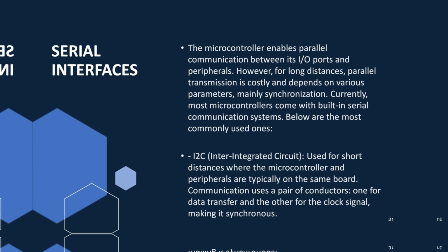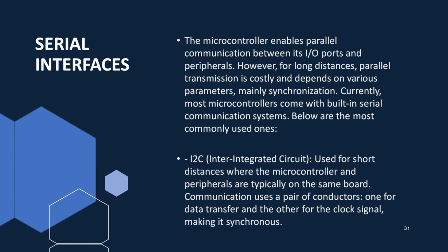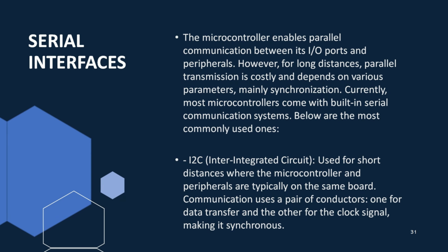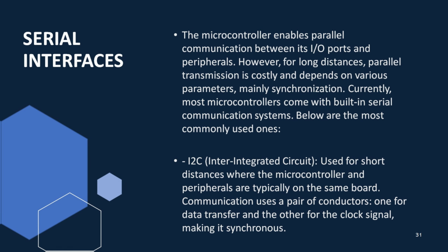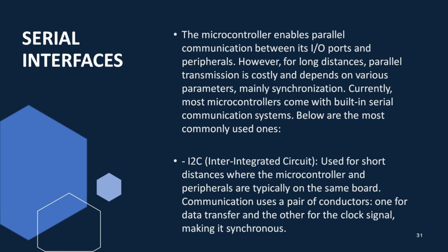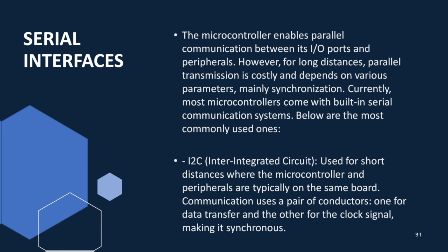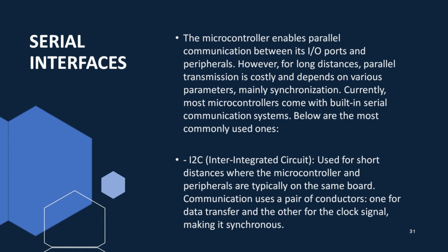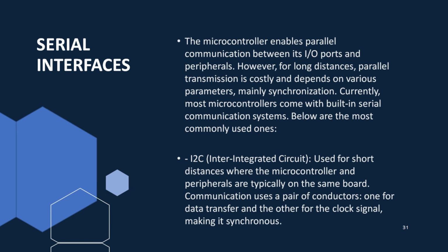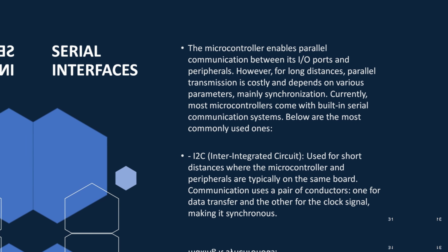Serial interfaces. While microcontrollers facilitate parallel communication between their I/O ports and peripherals, long-distance parallel transmission can be costly and subject to synchronization constraints. Hence, most modern microcontrollers integrate built-in serial communication systems. Here are the commonly utilized ones. I2C, inter-integrated circuit, employed for short-distance communication, typically within the same board where the microcontroller and peripherals reside. Communication utilizes a pair of conductors, one for data transfer and the other for the clock signal, ensuring synchronous operation.